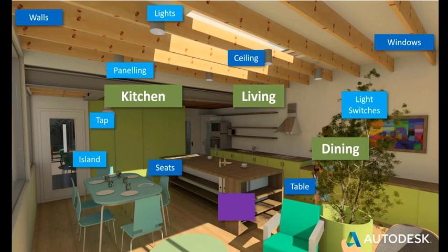elements. So essentially, this is how Revit and BIM authoring tools categorize information, is that it's contained within a building, within different spaces, and that's broken down into a hierarchy as suits your project. And all of this can even go down to the finer detail of different finishes that you want on your floor, the color of paint on the wall, and this can all be replicated and outputted to schedules and to spreadsheets and even to specification documents as well. So that's the benefits of working in a BIM process straight off.